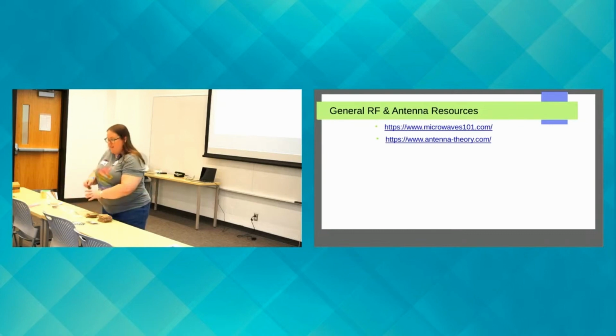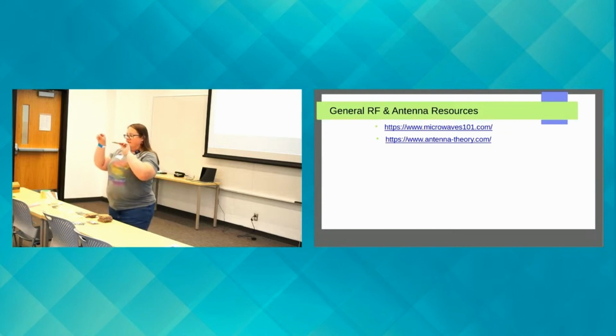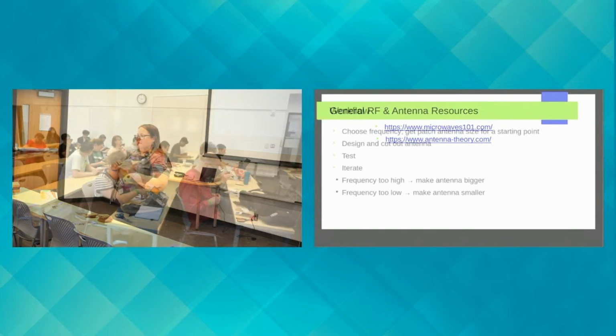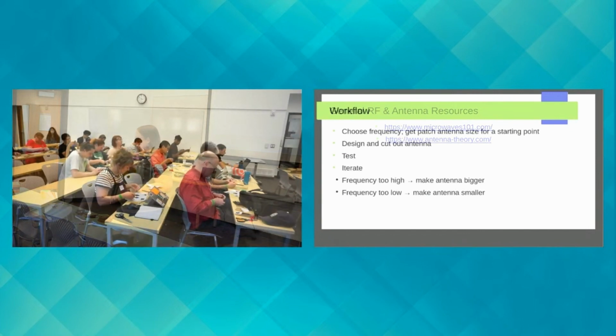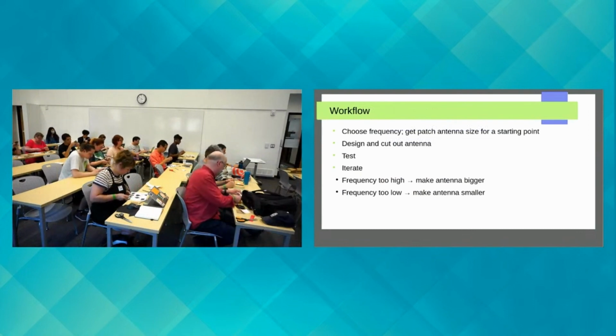And then after you've done that, you're going to take this little connector here. This is an SMA connector for a PCB edge. It just barely fits, so it's a press fit sort of thing. You just slide it on carefully so you don't scrunch up the tape. The tape is about 0.6 millimeters, I think, so it's quite fragile. And I have more up here. If you mess up a piece, don't worry about it. Come get another square.